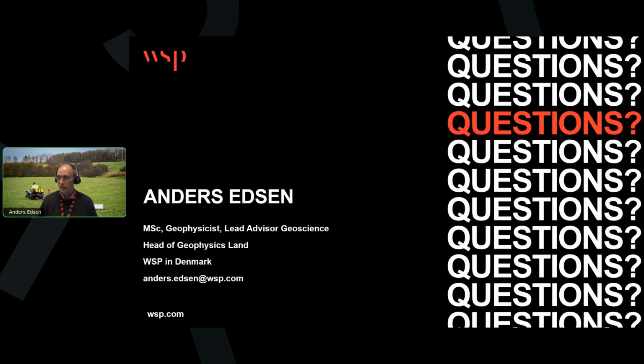Accuracy of EM methods versus ERT. That's a large question, and that's really depending on site as well. Generally, EM methods are best in determining low resistivity structures, and in most places water aquifers are defined by low resistivity structures being on both sides of the aquifers.